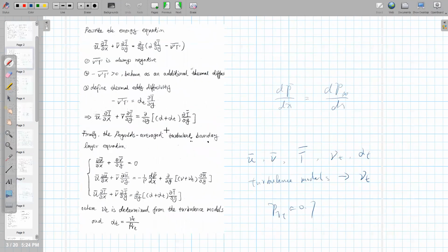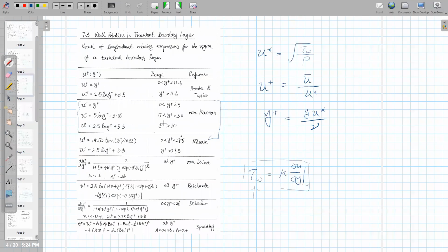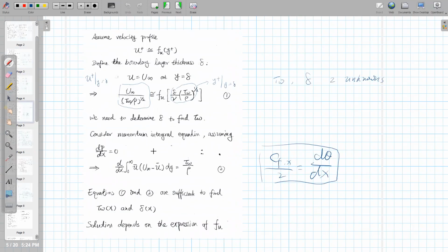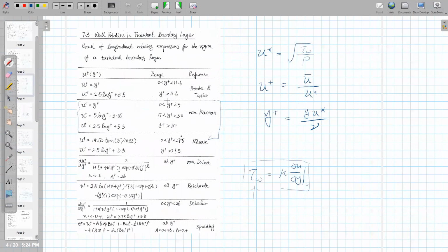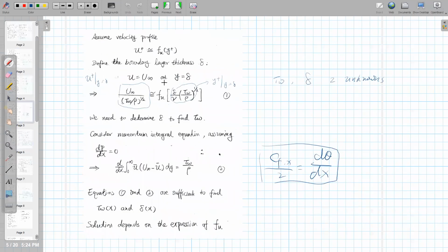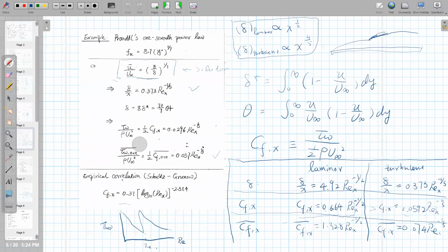And you also know how we get this equation. From the velocity field, for the friction, we get this result purely based on this velocity profile, which in most cases we assume is the 1/7 power law, and this solution is derived from this profile.